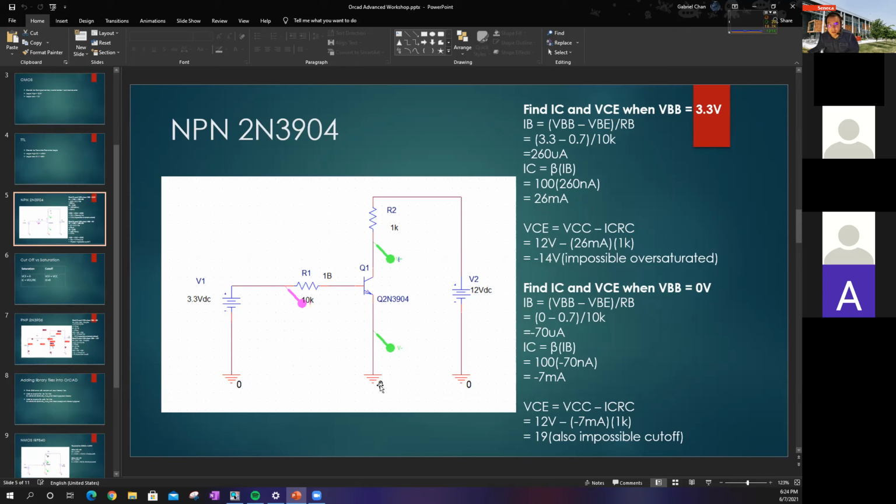Since the grounds are all connected, this will be connected as a circuit, but we're looking at this as a separate piece. This is how we figure out the current IB, the current running through the separate circuit. So IB will be around 260 microamps, which is small, but let's see if it's enough. Then there's beta, which is the multiplying factor of the transistor on the load side. Usually beta is around 10 to 30, but for our class, theoretically, we'll put it at 100.